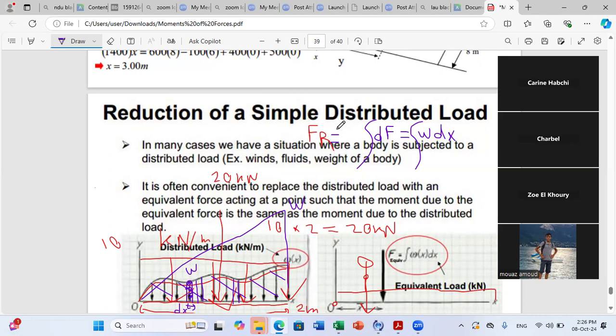This is step 1. But now, when you find the resultant force and you put it at O, you cannot put it at O without adding anything. You need to add the moment it's producing about O. And to calculate the moment it's producing about O, you say each elementary force here is at distance x from O. So for each small force, what is the moment?